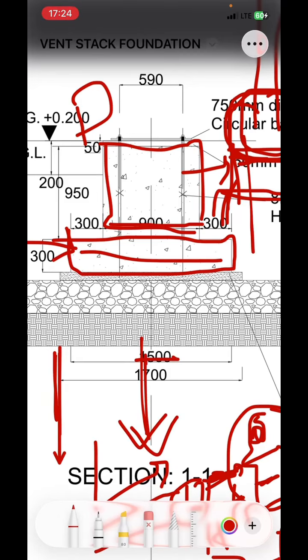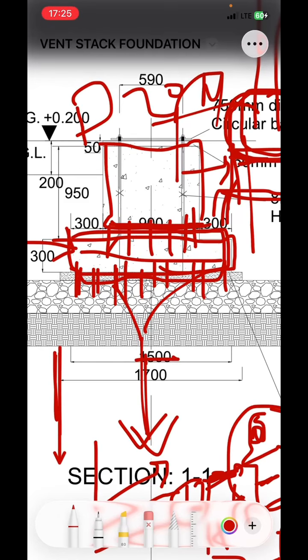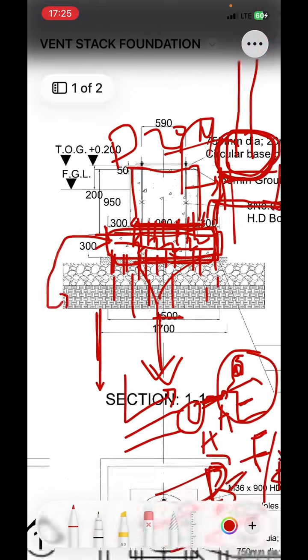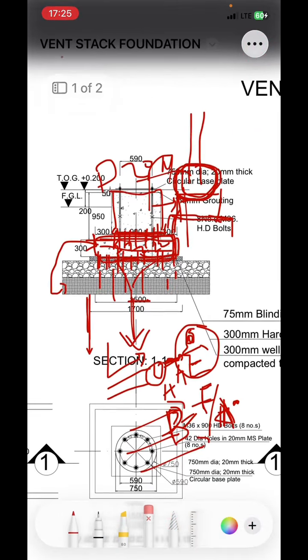It's not going to push, it's going to distribute it equally. So whatever force is there is going to be divided equally by the footer. You see, the base of the footer is going to divide that F equally. It's not going to concentrate it. Here now is a bit concentrated. You have some force coming down. If you now make it wider, let's say the entire force now is 20 Newton. Let's say 2 Newton, 2 Newton, 2 Newton, 2 Newton, 2 Newton at each point. So now that it is wider, then it will be 1 Newton, 1 Newton, 1 Newton, 1 Newton, 1 Newton. So it reduces the pressure. So that's the benefit of having the footer. Next thing